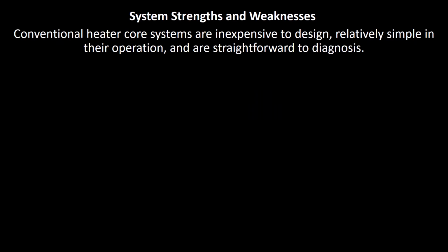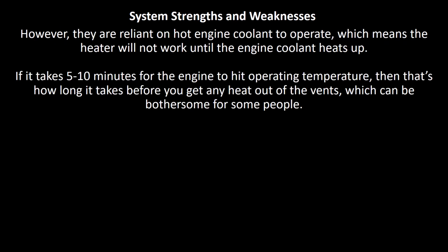What are the system strengths and weaknesses of this style? So conventional heater core systems are inexpensive to design, relatively simple in their operation, and they're straightforward to diagnose. However, they are reliant on hot engine coolant to operate, which means the heater will not work until the engine coolant heats up. If it takes 5 to 10 minutes for your engine to hit operating temperature, then that's how long it's going to take before you get any serious heat out of the vents, which can be bothersome for some people.